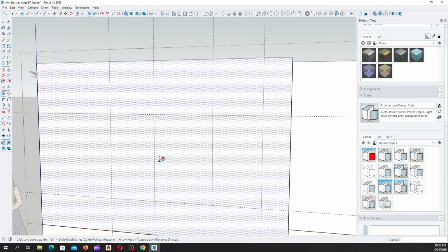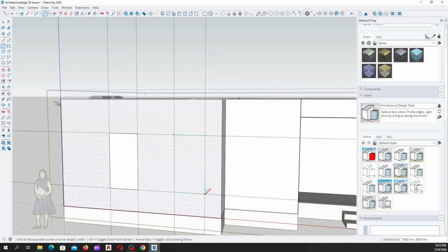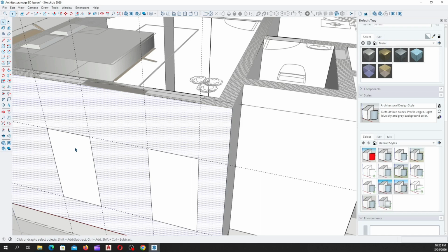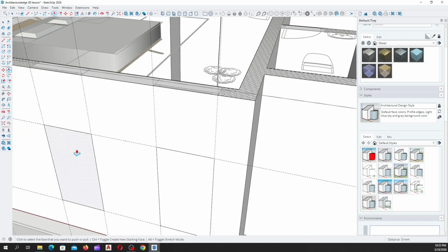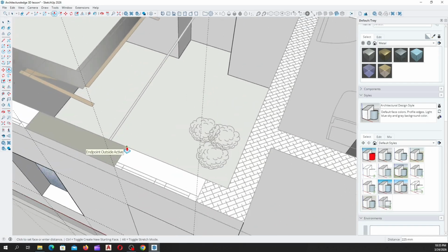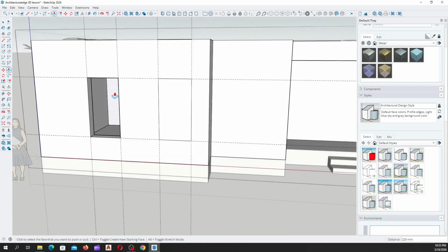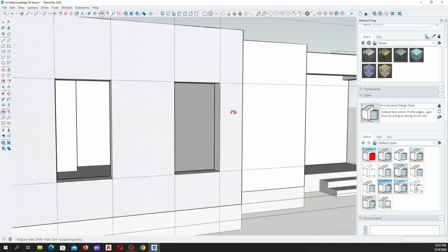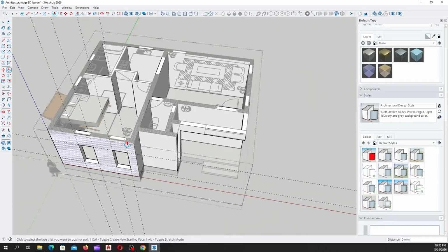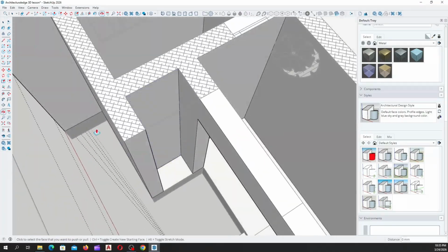Then this leads us to our right angle tool, which you can activate by tapping your R key on your keyboard. So we have this. Then after this will take us to our push tool. You tap your P on your keyboard. All right. Then you push. Then you can snap to this inner wall. As you can see, then we have this. Then you can just double click on this. It will repeat the previous push action.